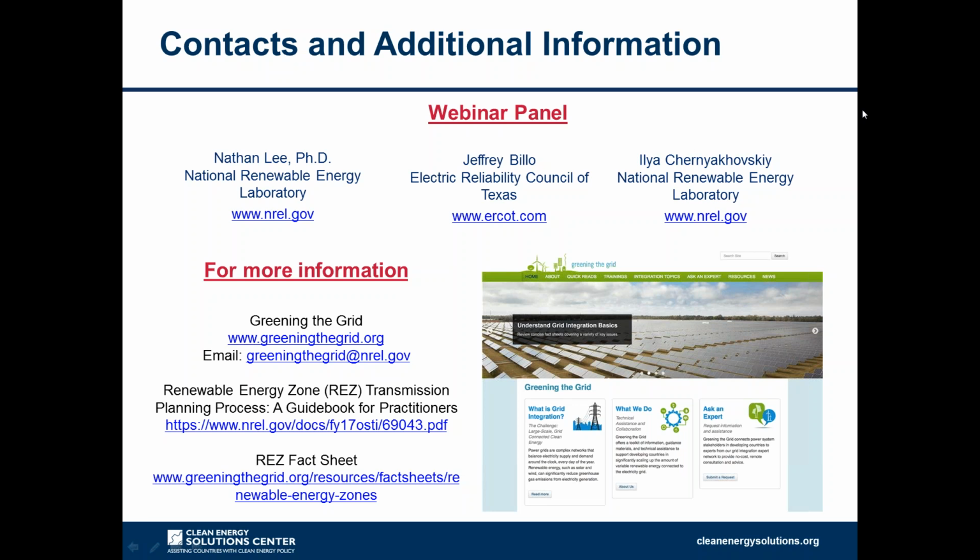We had many facilities that were constructed where we maybe only needed a single circuit in place in order to meet the CREZ objectives, but we recognized that there could be future expansion, and so we spec'd out the facilities to be double circuit capable, so that when needed, we could go back in later and add the second circuit on those towers. And we've actually already done that in a couple of cases where we've gone in and seen the need to add in a second circuit where maybe in CREZ there was only one circuit needed initially.